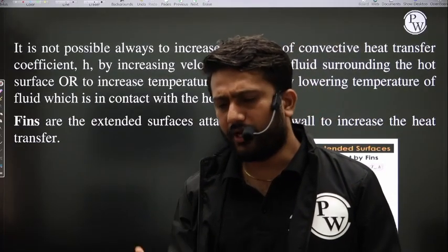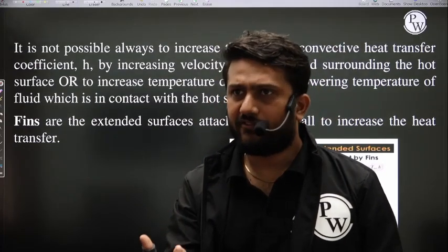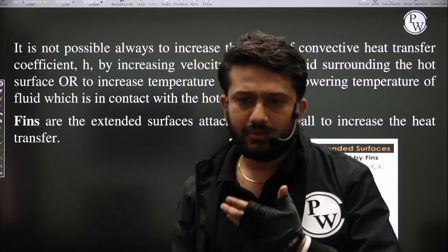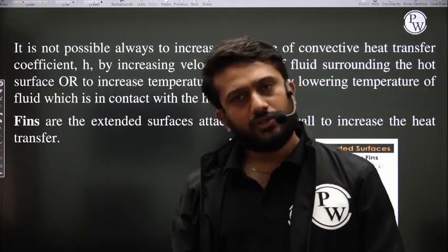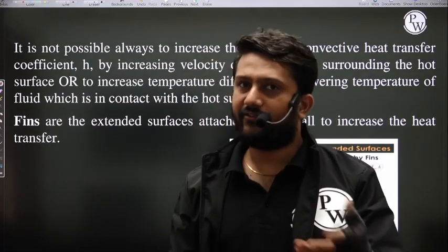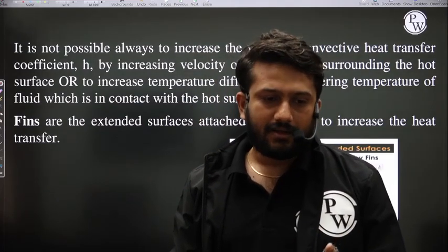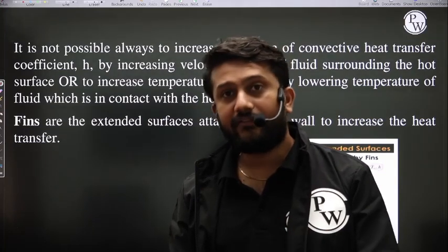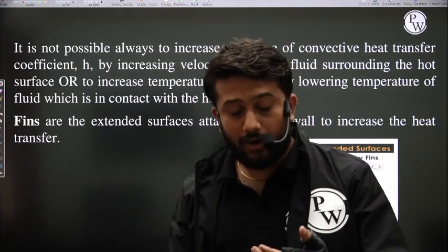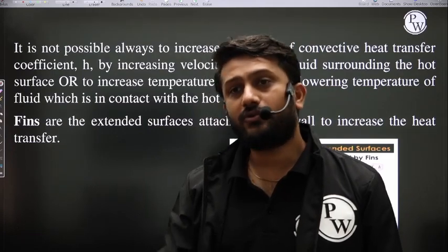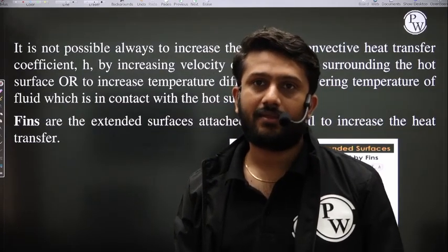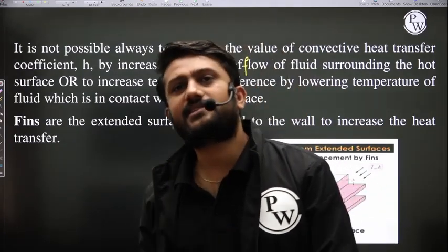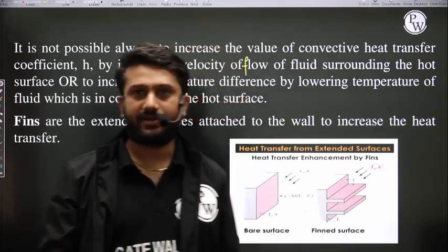That cooling pad consists of a smaller fan, and that fan is used to increase the rate of heat transfer. So yes, in some cases we definitely increase the convective heat transfer coefficient by providing fans, or by increasing the velocity of the flow surrounding the hot surface. But in some cases it is not possible, like a transformer.